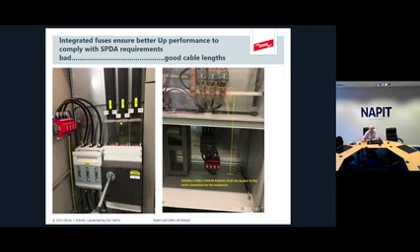And this is what we're going to be looking for, certainly on larger installations, and the same applies to distribution boards and consumer units. We take a connection from the phase bar through, in this case, a molded case breaker appropriate for the SPD in terms of its rupture capacity, and from the SPD a very short stubby cable to the metal case, which is earthed. All of that was done within 630 mil. That's absolutely bang on. That's exactly what we're looking for.